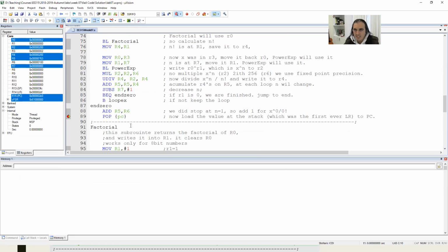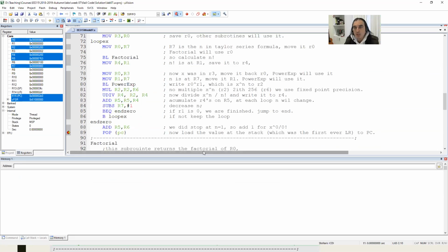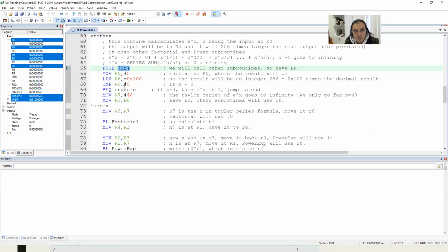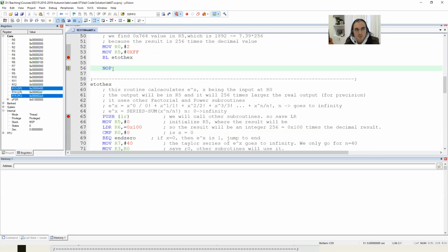So if you write something to the PC, it's actually jumping, branching. It should jump exactly to where the instruction memory points it. Now I'm ready to jump, because I'm going to jump here automatically. It jumped here automatically. This is the idea. This is what I've done theoretically with my pen, with my great talents. And this is what happens really in Keil. And this is how you should debug it.